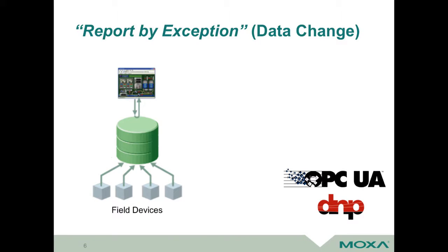Likewise, if I have a pressure that I want to sense, and that pressure doesn't change, I want to say if it changes by 1% or maybe 10 psi, I want it to send it. That's the basic fundamental aspect of this report by exception. You might hear the term, especially if you're a younger engineer, of push versus pull. The pull is the polling response. You have to ask for it and pull it out. This is more of the push response, report by exception.